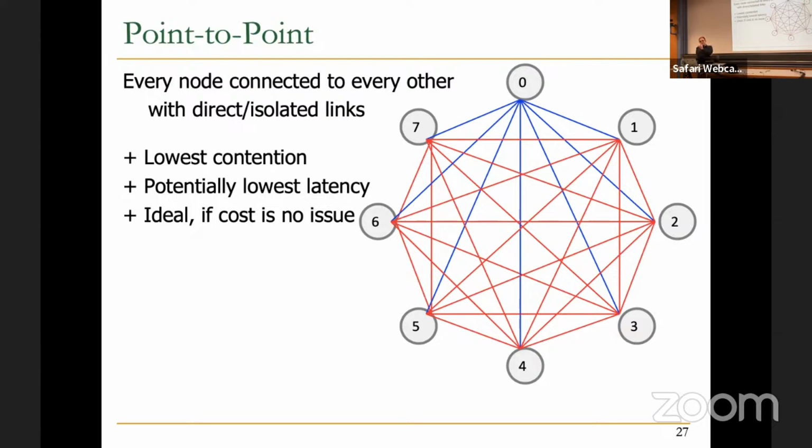That brings me to the part where I said easy to implement or easy to build. Once you want to make this point-to-point connection on your chip, it's not possible, right? I mean, it's possible, but some of these wires cannot easily connect to the destination because of the contention of the wire routing. So then it will make some wires longer and longer, and that long wire would have higher latency. And in the end, you might not actually have the best latency. So I would say it can provide the best latency if your network is highly contended, because then your link latency is not really a bottleneck.